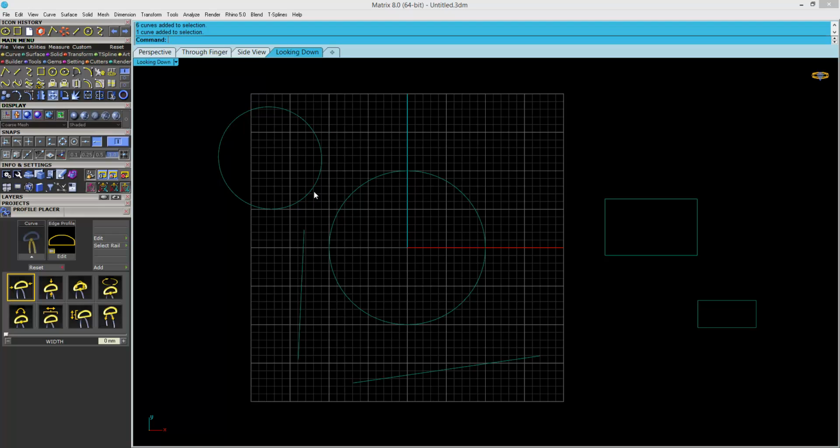And the third way of selecting is to click on it, and it will get selected. Which was the first one? The first one was the dotted box, and this was the complete box, and then you click on it for selection. But if you need to select more than one, you click on it, then press shift, and then you can continue adding more objects to your selection. And if you need to remove something, you need to press control.